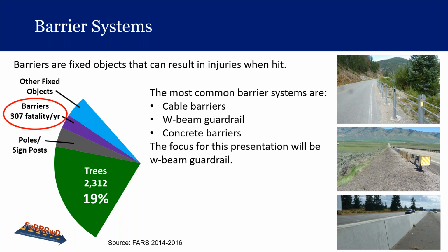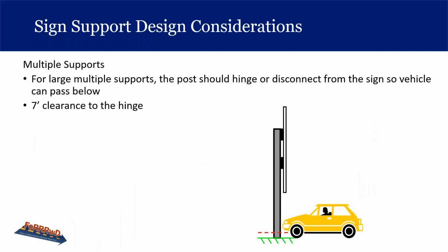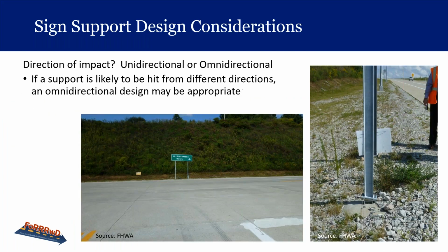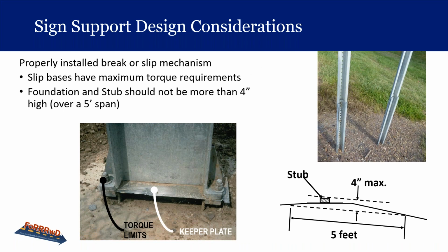So they wanted you to elaborate on overlap connections at the ground surface. Yeah, and this picture on the right, what we're shooting for is you're measuring from the ground 4 inches, and that should be the max. So when this breaks away, if it's more than 4 inches, it has a probability of snagging on the vehicle.